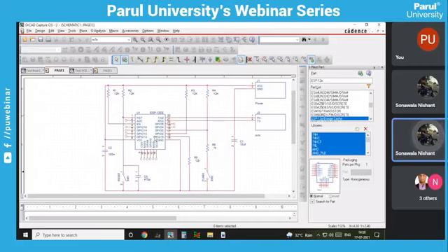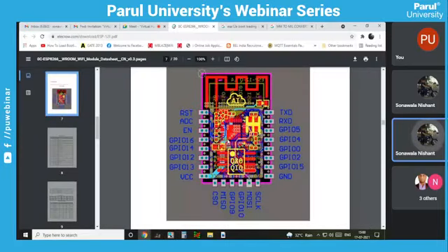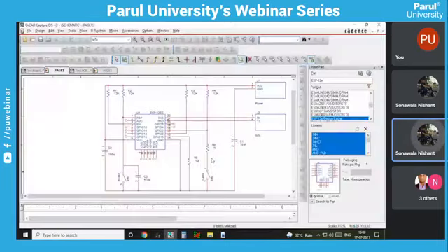Like we can go with MQTT, then Constrained Application Protocol, then AMQP, Advanced Message Queuing Protocol. These are the IoT protocols. So we can integrate them with our program and make an application. Before designing a program, suppose you have created a program, how can you install that program into your ESP? For that you require a bootloader circuit, right? So this ESP controller or ESP module requires a bootloader circuit. So I have created a bootloader circuit for this ESP12.